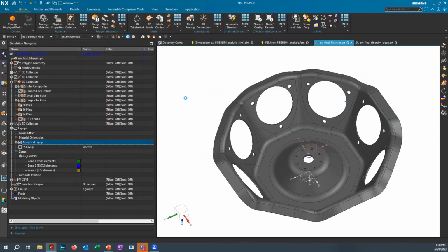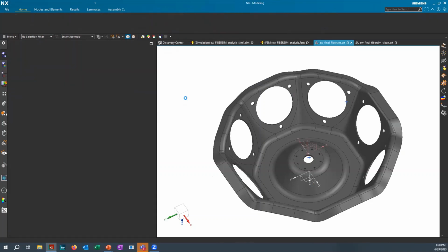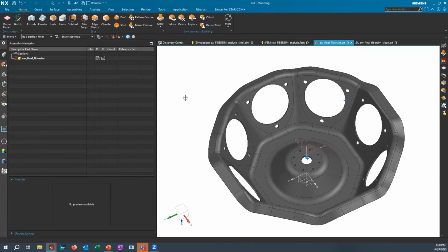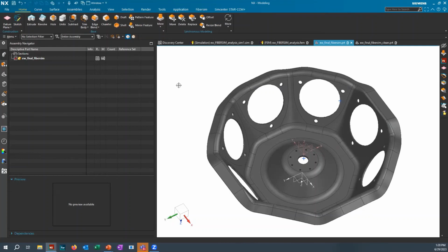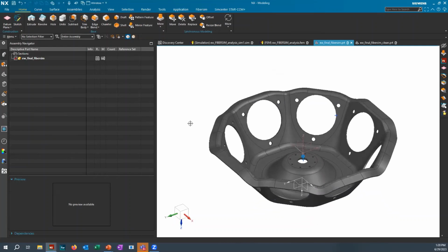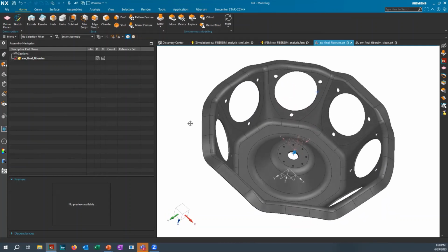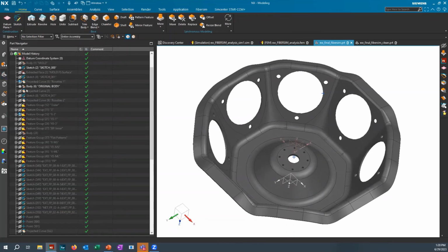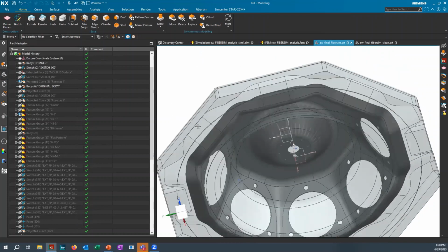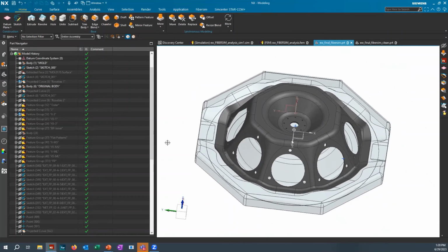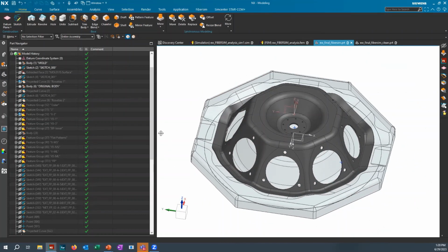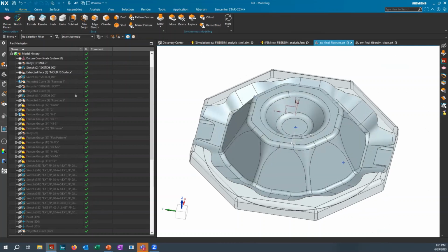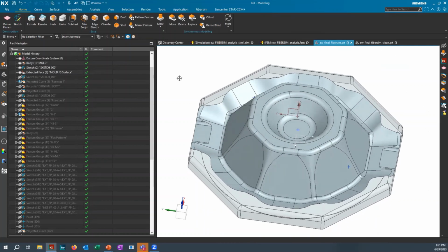So on the other side, while the analyst is working on getting this data, the Fibersim engineer is likely creating the mold surfaces and prepping the model for the development. So here we have the actual final piece shown here from a CAD model standpoint. And here he would likely generate a mold that we're going to be laying up on. So this is actually the mold that was used for the manufacturing process. And then from this, we're going to actually choose an analytical surface for Fibersim.